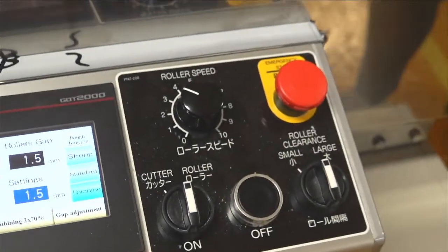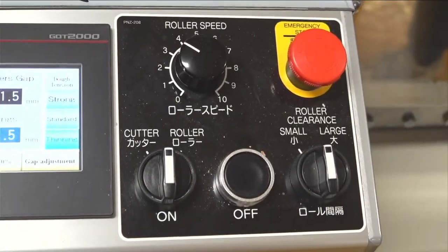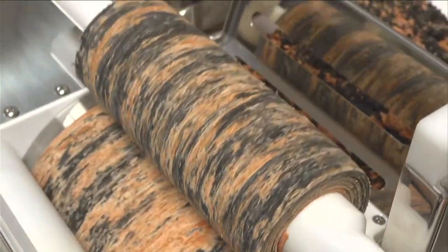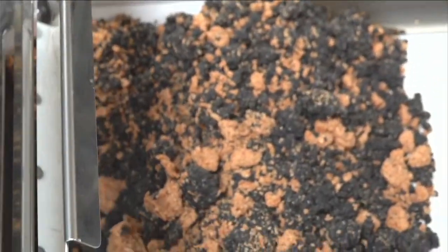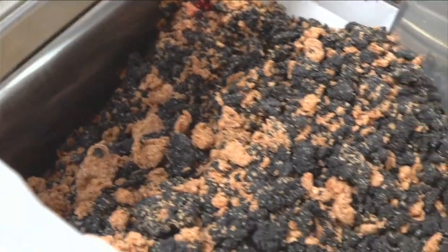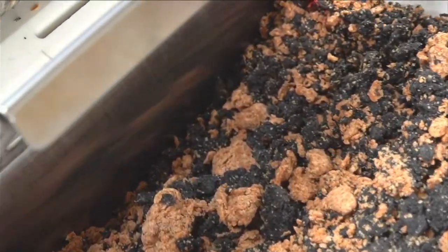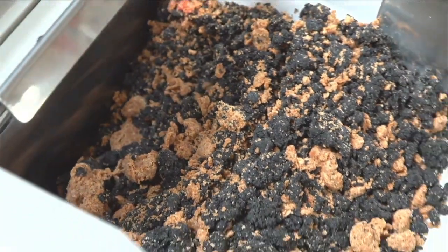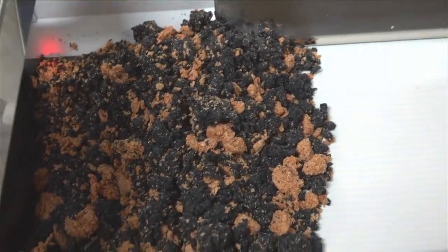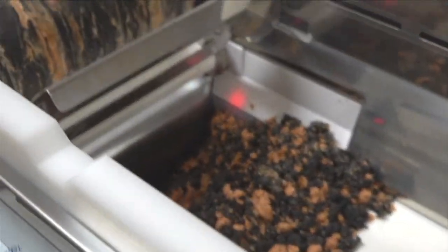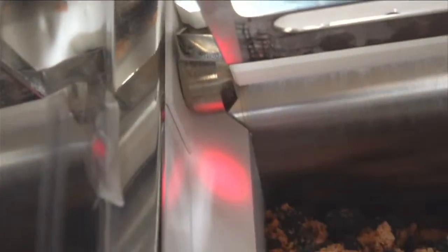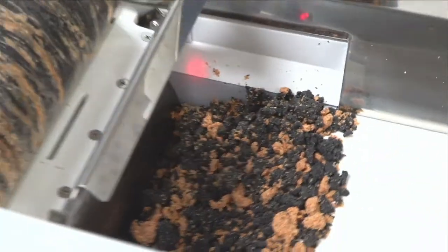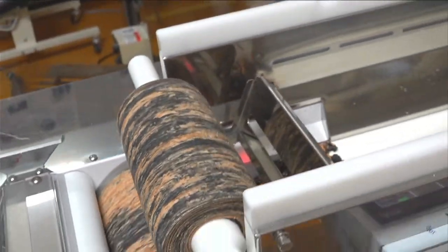And then so it's automatic after, or maybe just wind the first edge of the dough, and then it just goes in automatically, right? And then the machine is actually measuring how much dough is going in, because the sensor is seeing how much dough is being fed, and depending on that, it's controlling the speed of the conveyor, right? If it's going too much, we're going to slow it down.